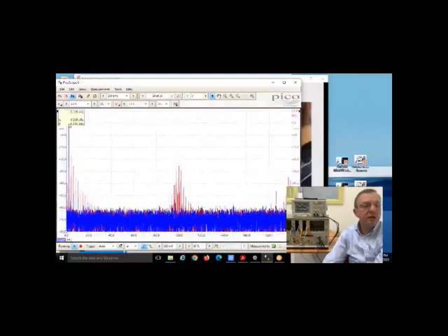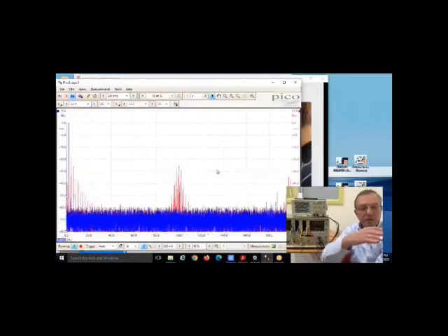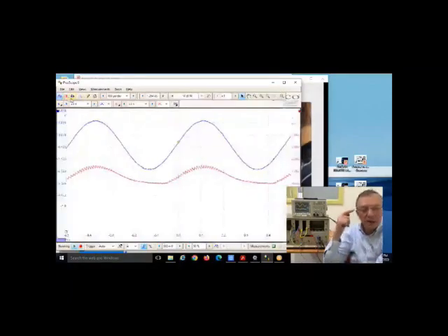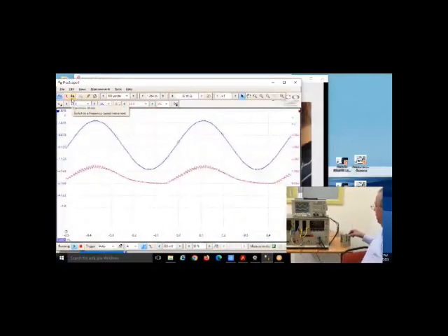So there's the 2 kilohertz message, and because we're using an RC filter, you can see from the roll-off that it's passing some 100 kilohertz components. So it makes sense. So now we're introducing the concept of an RC filter compared to a 5th order filter.